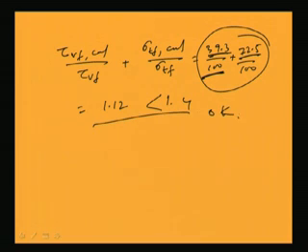So, this second method for the cold driven rivet is more accurate than the earlier one, because here the neutral axis depth has been calculated accurately. In the other process the neutral axis depth has been considered as h by 7, but definitely it is not exactly at h by 7, it depends on other issues. So, that has to be calculated properly. So, if we want to calculate properly, we have to follow the second method.